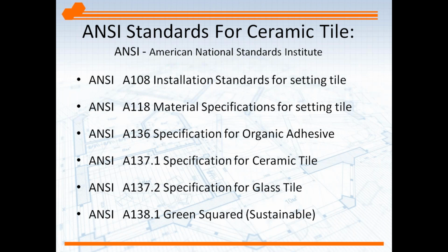ANSI 118 is the standards for the products themselves. So what makes up the grout? What are the components, the performance characteristics? If I say a grout meets an ANSI 118.7, which is a cement grout standard, you'll know that that grout meets all those standards that go with that classification, including the ASTMs for flexural strength, bonding, freeze thaw, compression or PSI. So those things are built in when you say a grout meets that standard. And that is, of course, obviously found in the ANSI catalog.